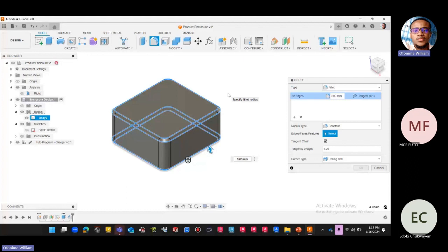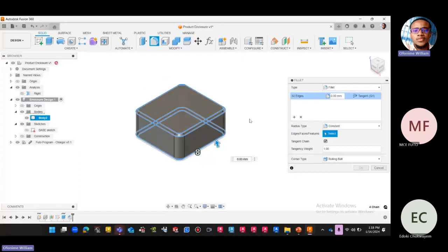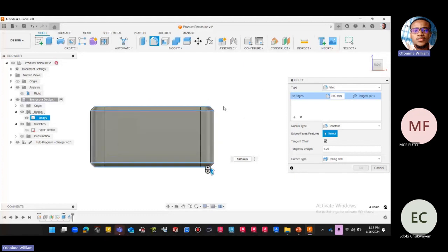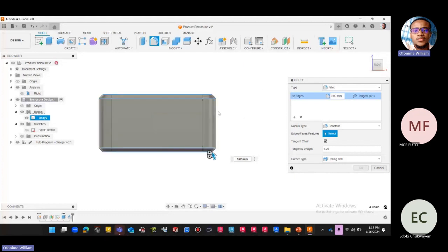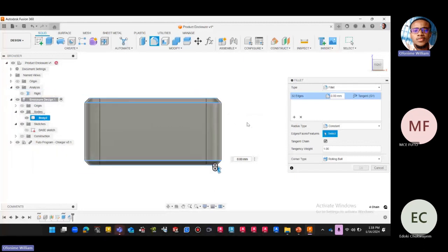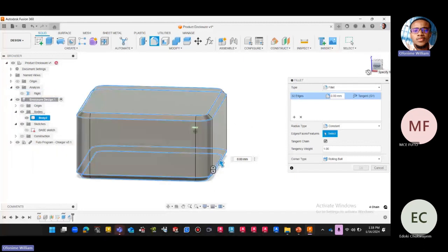So one of the ways to handle this is what we call a fillet. That's why we call in the fillet command. It helps you distribute that stress and makes sure that you're not having one place where you just press a side and the thing breaks into two or cracks or something like that. So it's not just helping you make it look smooth, not just for beauty. It's also having a natural, functional purpose.